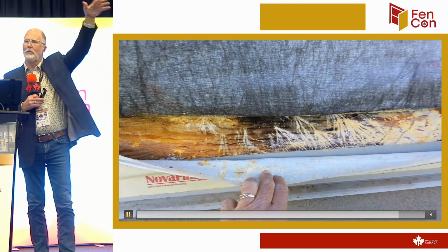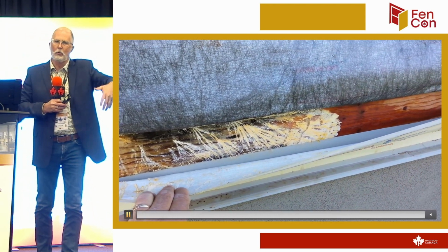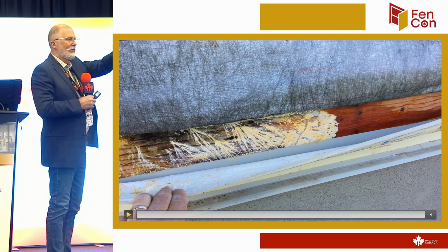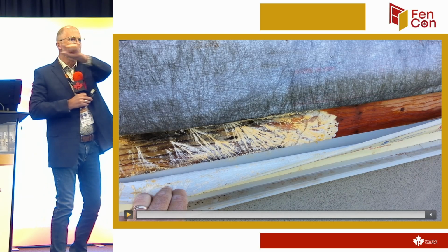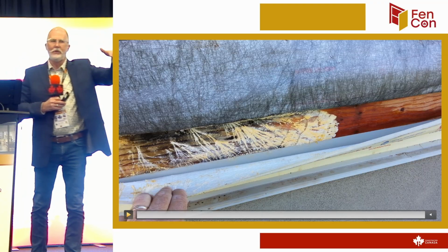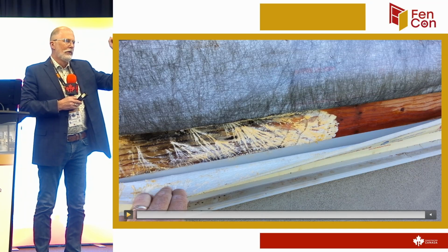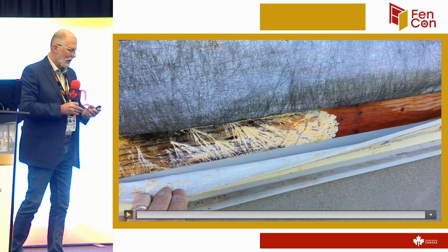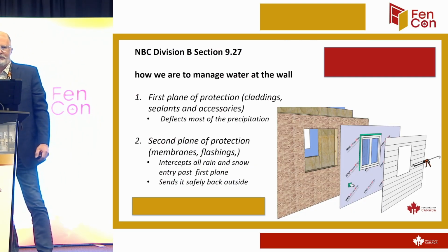The water was getting up into the soffits. It was running down behind the whole wall. And guess what you have in the sheathing? Joints. The water goes into the joint. Now it's on the inside. So even if you sealed the head of the window, the water's already on the inside of that opening. So the water ends up at the bottom on the sill. So how do you protect against that creating problems?